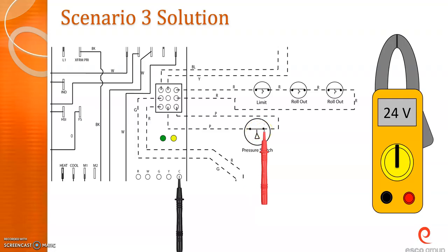At that point, you'd want to actually go to the pressure switch and make sure that everything's plugged up right, and then check your inducer. You're going to check your vent pipes, make sure that nothing's in those pipes, that there's not a bird's nest, snow or water buildup or anything in that, and even in your inducer chamber itself. If you get anything in there that's going to stop up airflow for that draft, then that's not going to allow that pressure switch to close.